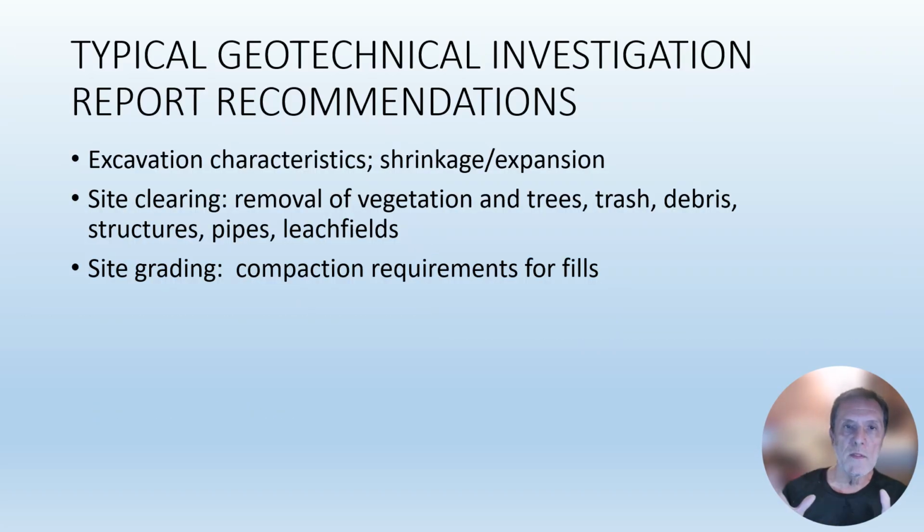Okay? So you have done the geotechnical investigation. You have a copy of the geotechnical investigation report. You have the recommendations that go through excavation, shrinkage, and expansion of materials. That means, let me put it this way, when a firm, dense soil is excavated and then put back as compacted engineered fill, it won't have the same density as it had before.